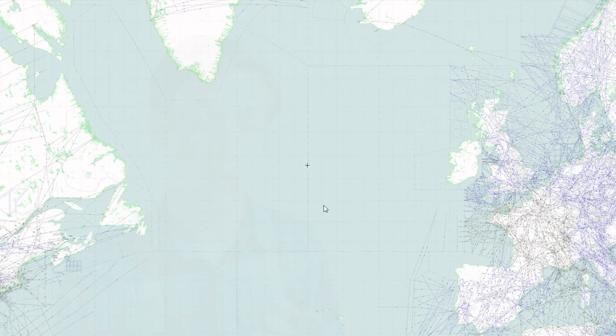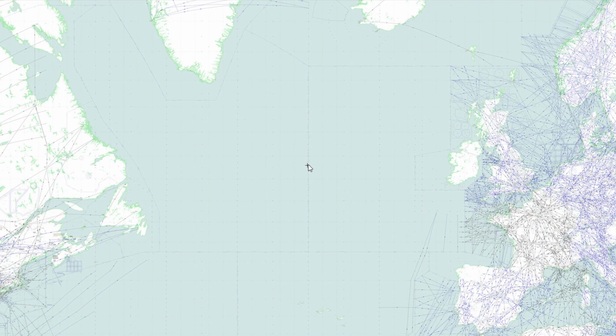So in that case, if you're flying outside of the valid time period, you'll basically just be flying a random route instead of a true NAT track. To determine whether you need to file a random route or to actually file a NAT track, one way you can look at this is by looking at what time you will cross the 30 West waypoint.